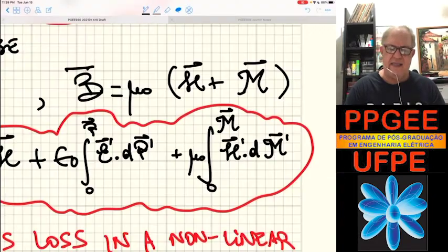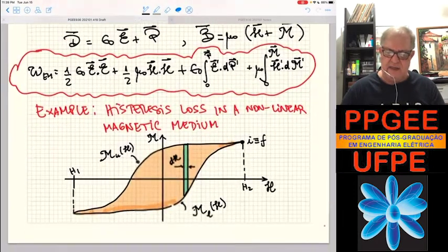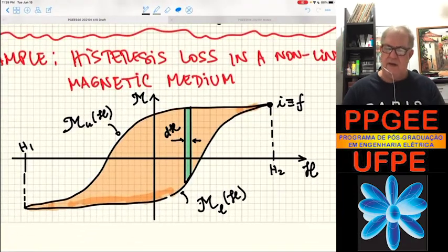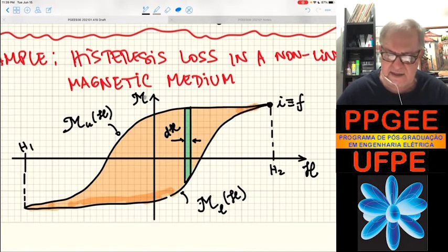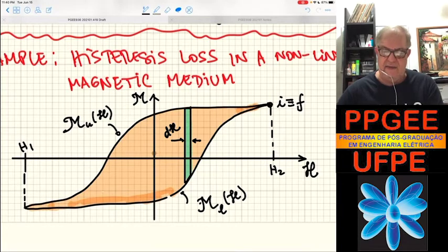We can look at that by looking into the hysteresis loop, something like this. The core has a hysteresis area like this one, in which H is the magnetic field and M is the magnetization. On a cycle, you can start here in the initial value, or you can start here and magnetize, then you start entering the loop.